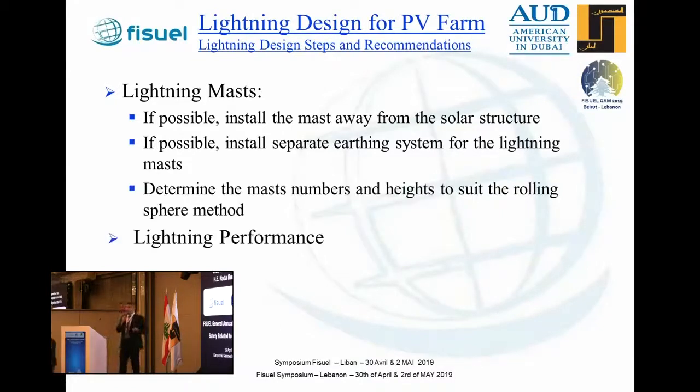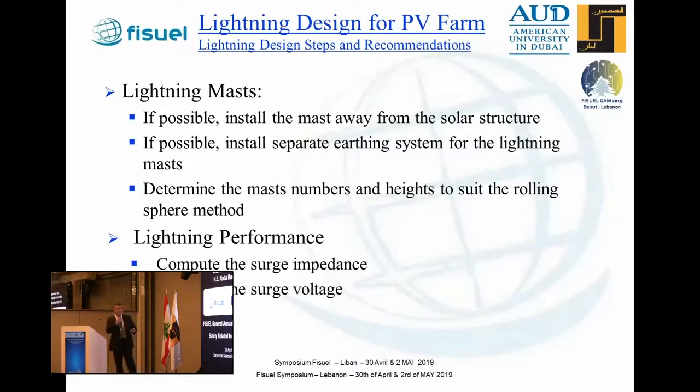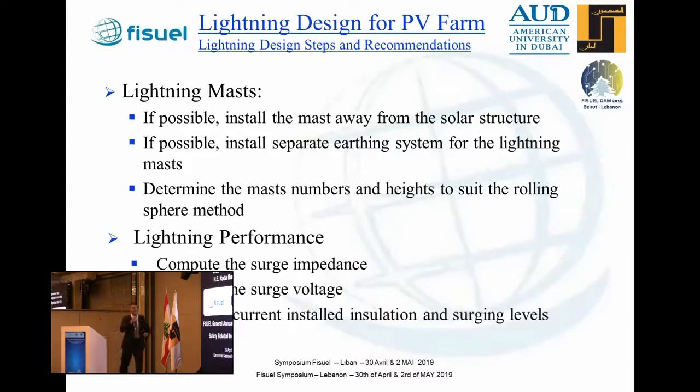And at the end, we do the lightning performance. Compute the surge impedance, compute the surge voltage, and verify that the currently installed insulation and surge level meet the V surge due to a lightning strike. And at the end, you proceed with the design report.